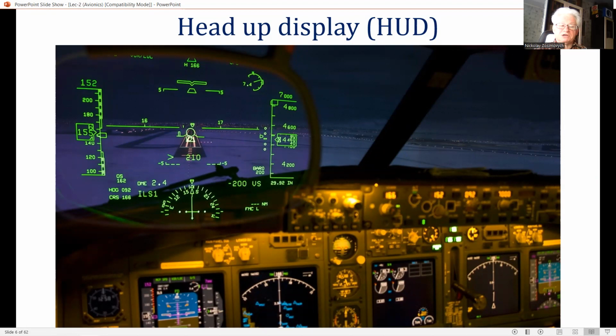The fundamental importance of collimating the display cannot be overemphasized and will be explained in more detail a bit later. Because the display is collimated, that is focused at infinity or a long distance ahead, the pilot's gaze angle to the display symbology does not change with head movement, so that the overlaid symbology remains conformal, or established, with the outside scene.